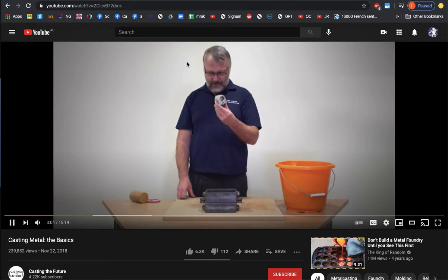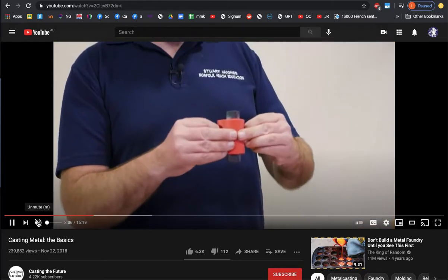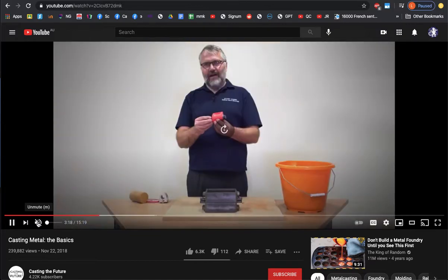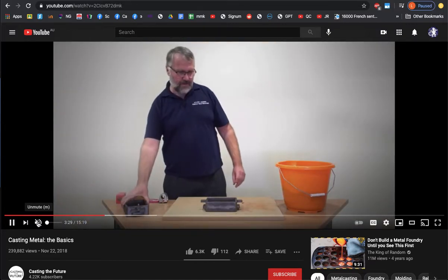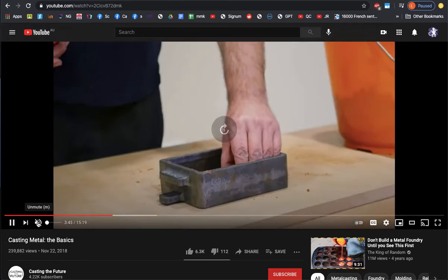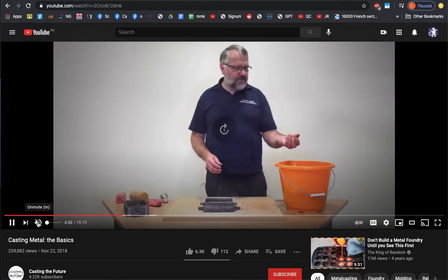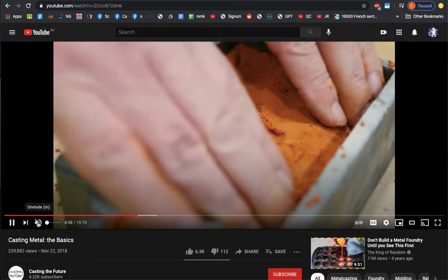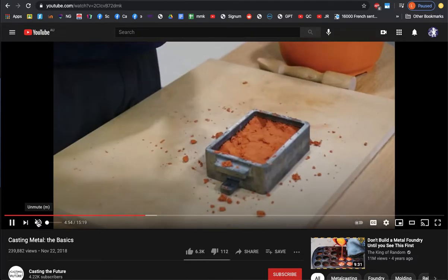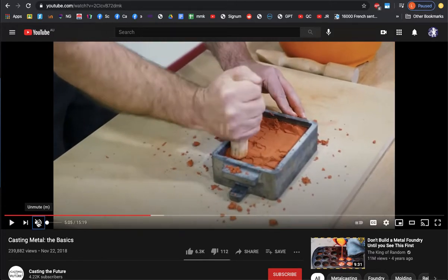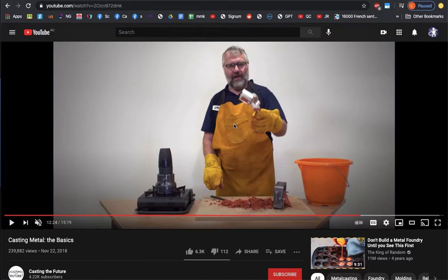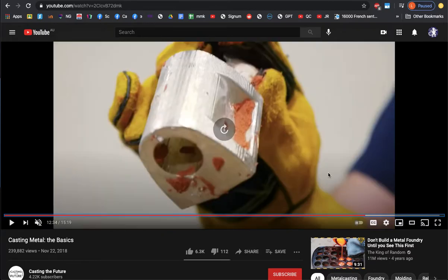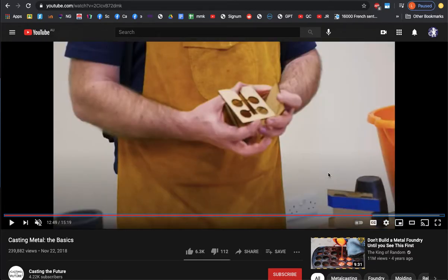This video here is good because the guy gives a lot of description about the different parts. He names the cope and drag. He talks about how he casts a cylinder. He goes into some detail. So he's using a different coloured sand or a different binding agent to hold the sand together. I won't go into that video because it's fairly long, but he's giving a lot more detail about how he's making his process. What he does do that's interesting at the end is he also uses a die cast method.